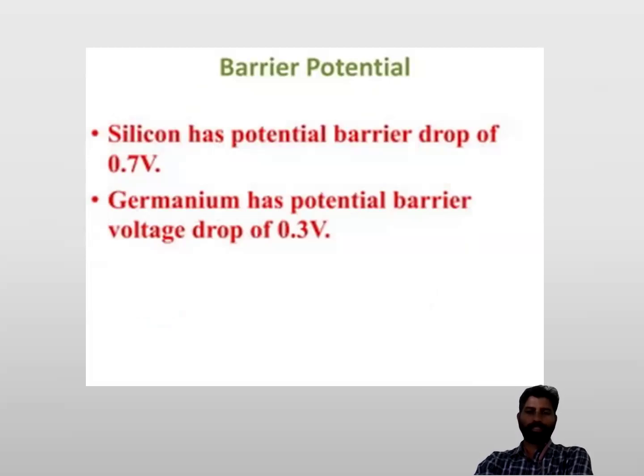If you are using silicon material, the potential value of this wall is up to 0.7 volts. For germanium material, the potential value is up to 0.3 volts. The depletion region acts as an insulator, so to overcome that insulator and get current conduction in the silicon material, you need to apply a voltage to break the barrier potential, of at least 0.7 volts or more than 0.7 volts.